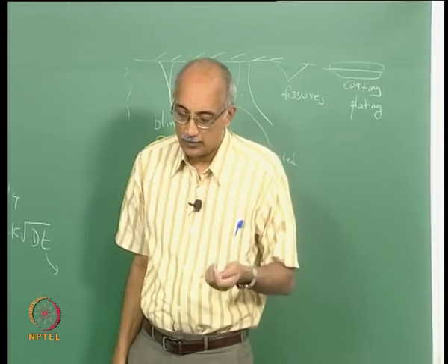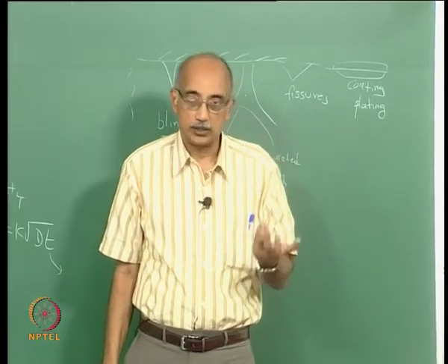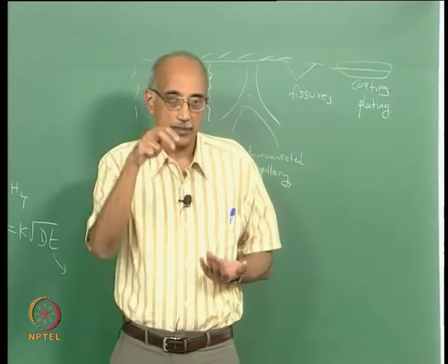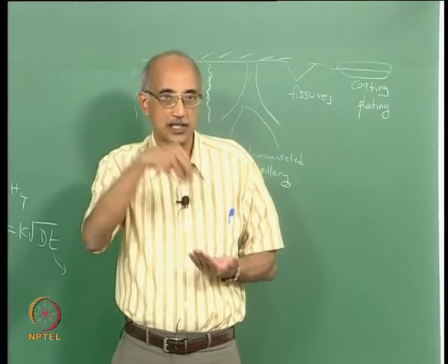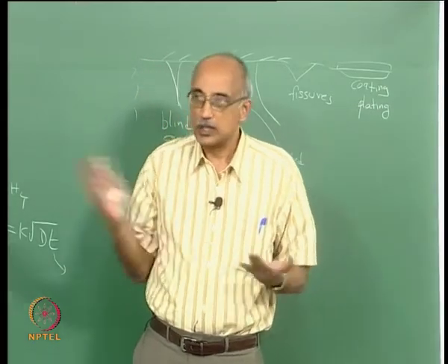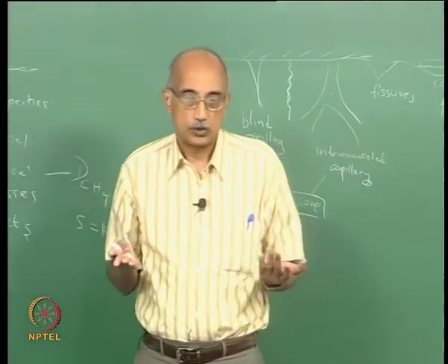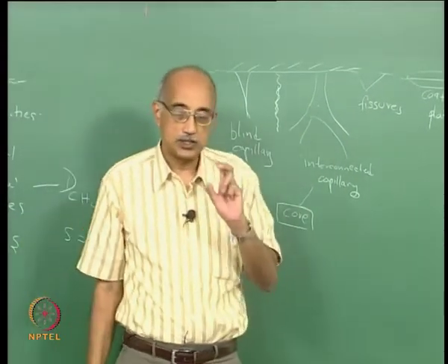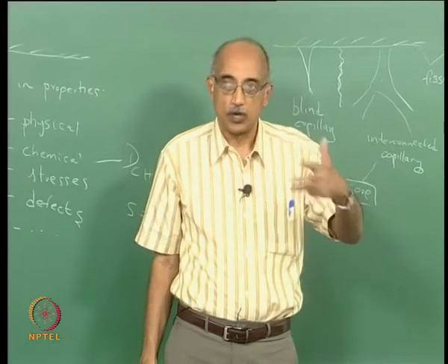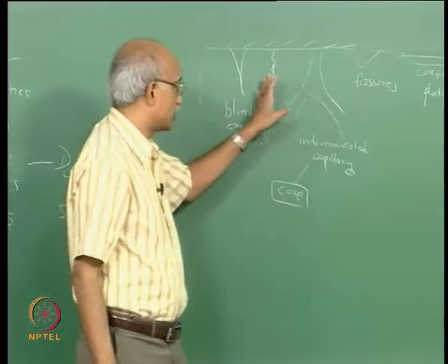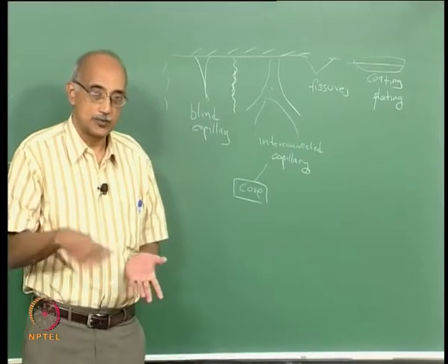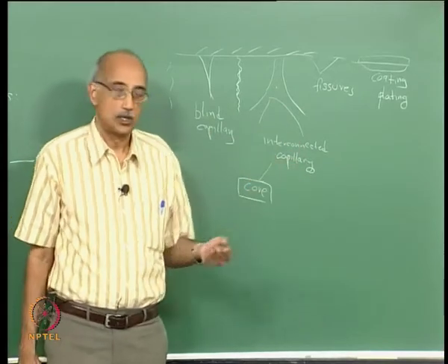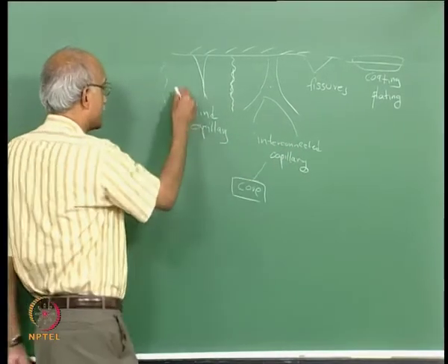So if you do a metallographic analysis of the material, of the particle, you do a cross section and actually look at the particle and its structure by depth as you go from the outer surface to the center or the nucleus of the particle, you will see all these things. On the surface you will see essentially the surface characteristics, and if you have a very sensitive way of detecting, you will see the three-dimensional morphology of the surface. But the amount of detail that you see will increase when you go to the subsurface region because of the presence of all these different things that can happen, and at the same time you are seeing all these gradients, right?